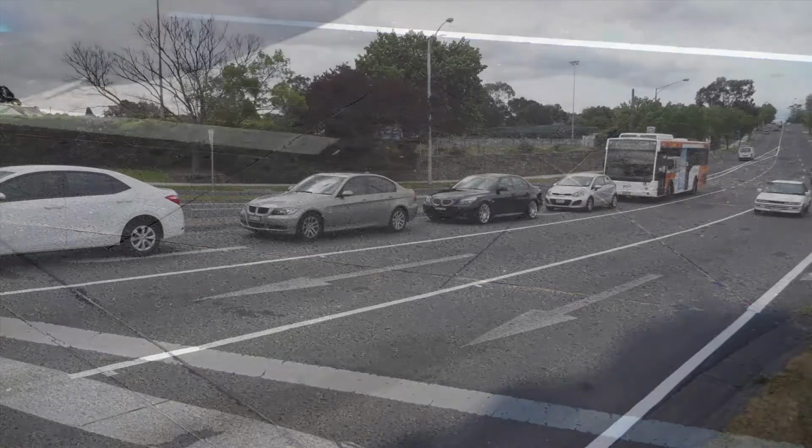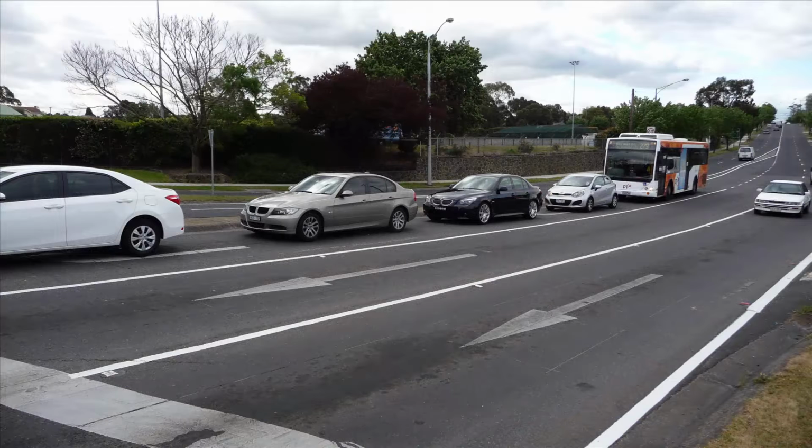These are fitted at the intersection during installation, and once installed, essentially there is little opportunity provided for adjustment or fine-tuning. Moreover, if the detector is not placed far enough in advance of the intersection, a bus may become caught in a queue of vehicles, delaying its arrival at the installed detector and therefore creating further delays for the vehicle.